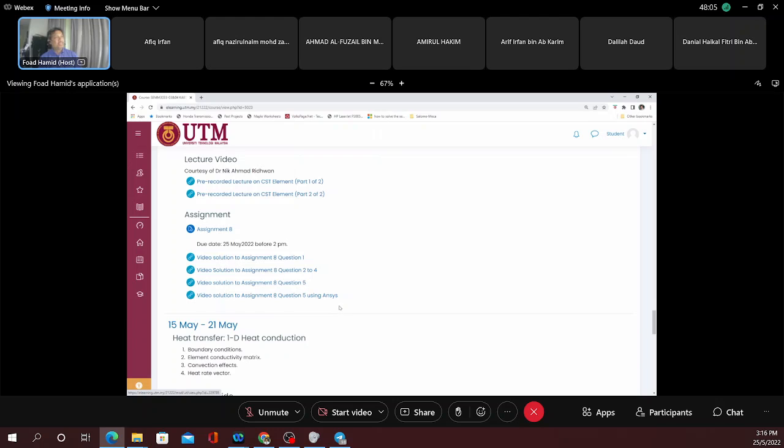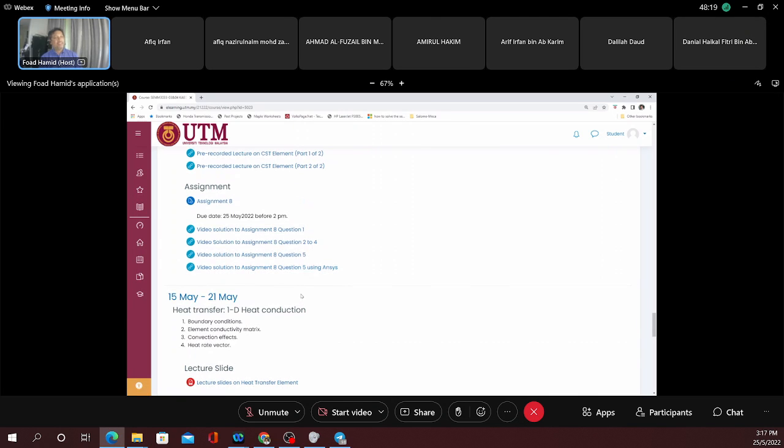So you need to see my video on how I tweak it such that ANSYS only uses triangular elements, not a combination of both triangular and quadrilateral. Use a minimum of 12, and by identifying all boundary conditions, do a finite element analysis on the quarter model of the plate.